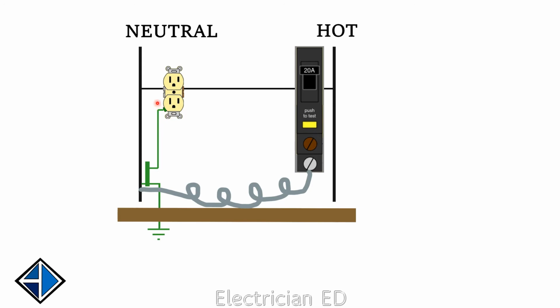Okay, and then we also have to do something about this too. If we're going to protect this outlet, then we need to change this, because this is now our neutral connection back to the source. We need to bring this over to here. So we'll break that connection right there, and we'll join it up over here.